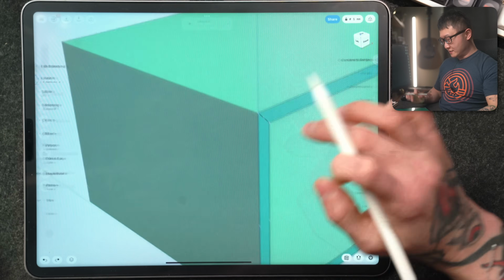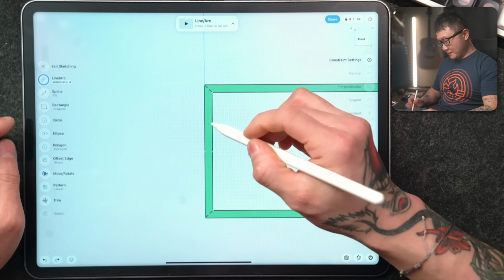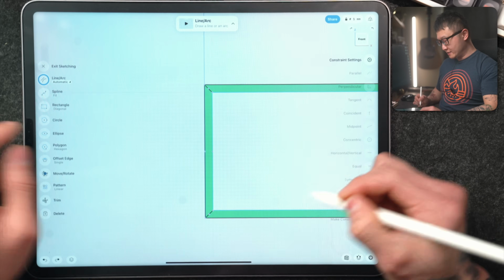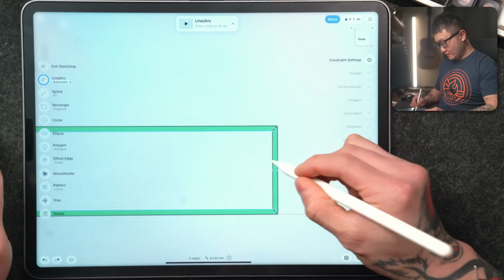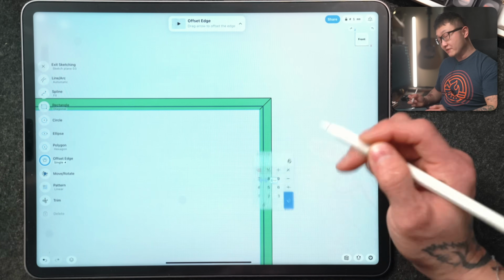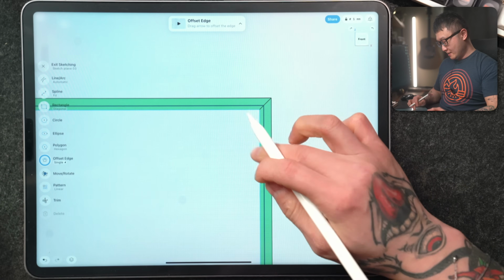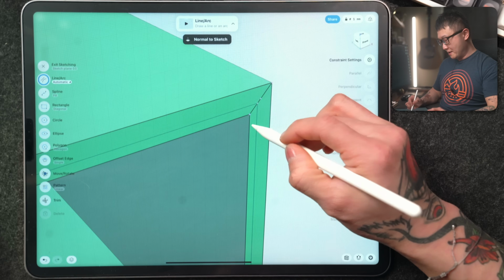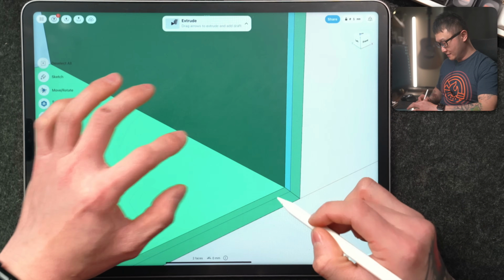And we're actually going to do the same thing and create a deeper rabbet on the front side as well. It was something I did on another media console that I built a while ago, and I just really love the way that looked. So we're going to do the same thing here. Let's rotate to the front side and we're going to start our sketch. So just like before, we're going to pick the inside edges on all four panels and then use the offset edge tool to push this out 7 millimeters this time. And then let's come in here and pick these four surfaces.